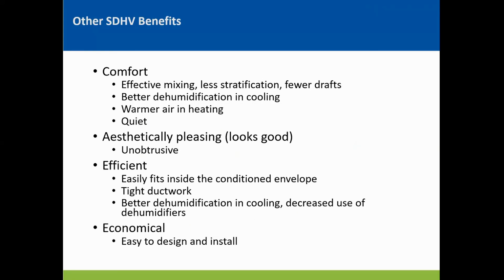Well, small duct high velocity has other benefits besides those two. Obviously, comfort is a big one, and this is done by having good mixing, better dehumidification, which we've talked about. Also, warmer air if you're heating with a heat pump. It has to be quiet. It's part of being comfortable. It has to look good. Nothing is less unobtrusive than a 2-inch hole in the ceiling, and of course, it has to be efficient, and